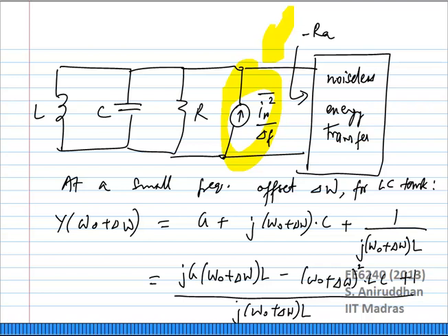So what kind of frequency dependence does it have? That is right. So what happens is, if you look at this negative resistance, first of all, it's not a linear resistor. What we have been saying is, due to the behavior of the circuit, during different portions the transistors go through multiple regions. At the end of one period, you have restored whatever energy was lost in the resistor.